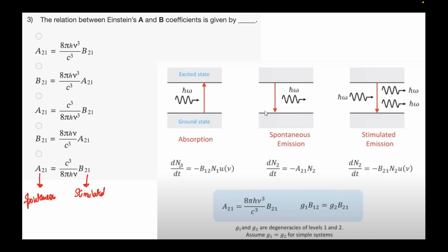So again, this is the same logic. We want to find the rate. It will depend on n1 with a negative dependence. n1 is the electrons, let's say here, n2 here, this is the energy state E2, this is the energy state E1. So it will depend on n1, and it will also depend on the spectral density. Why? Because if your h nu is less than your Eg, just imagine that case, then there cannot be any absorption. So that's what I was saying, this is a very powerful term in the sense that it will dictate how the system will behave.